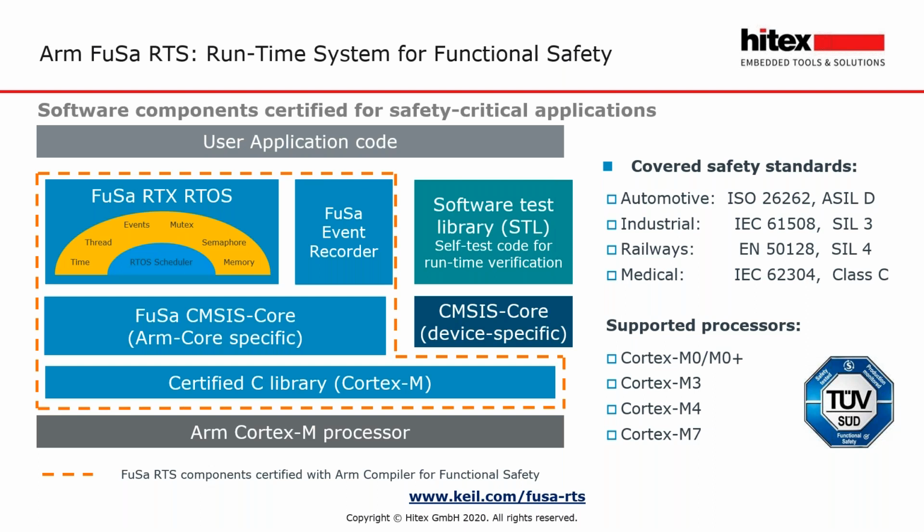In addition to the runtime system, there are a number of software test libraries. So these are separate products which are purchased separately through ARM, but these are software test libraries for their different Cortex-M processors. Some of these software test libraries are now available directly from the silicon vendors as well. And they will attempt to exercise every gate on the processor to validate the operation of the processor core at startup. Now, you think you might be able to write one of those yourself, but it's actually quite a difficult thing to do.